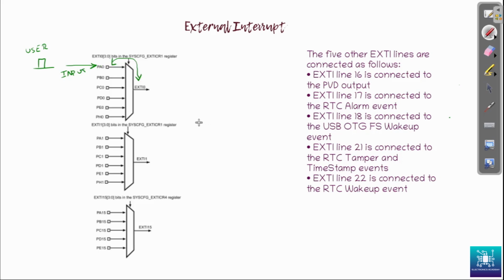After that, we need to take a few more steps to configure this interrupt. The first one is the physical configuration, where we open up port A. So we have to enable the entire port A, that is, enable the clock for the port. Then we configure port A as an input port, link the port logically to EXTI0, and then do some EXTI0 interrupt configuration in the NVIC, for example setting its priority and enabling the interrupt, which we shall see in the code and the upcoming slides that you have already seen previously.